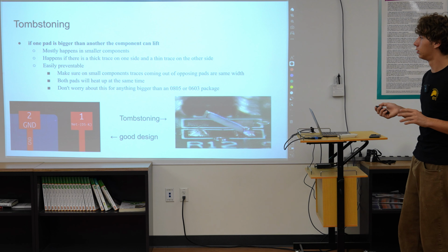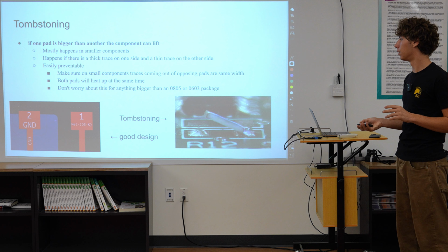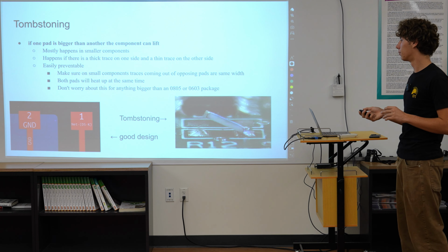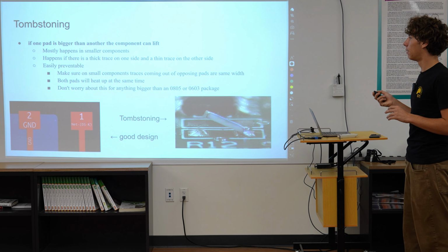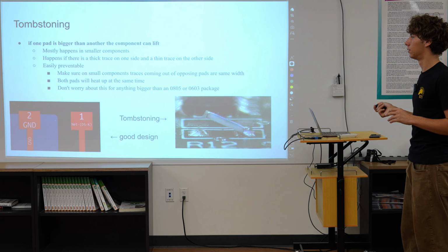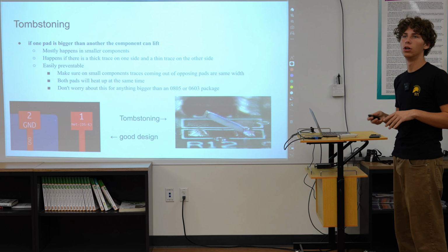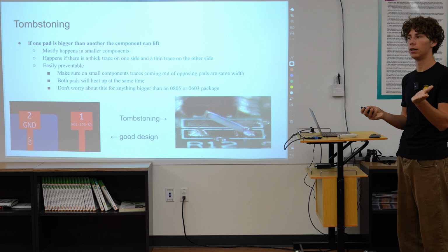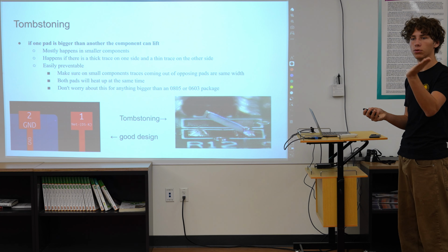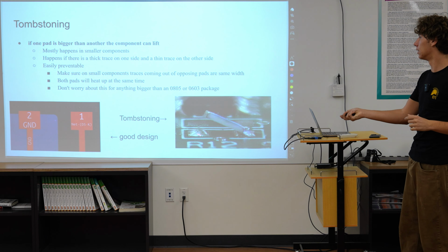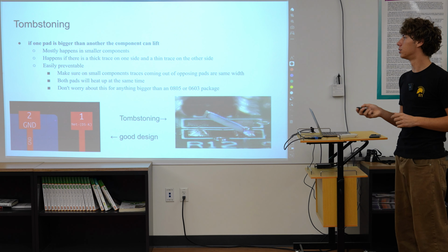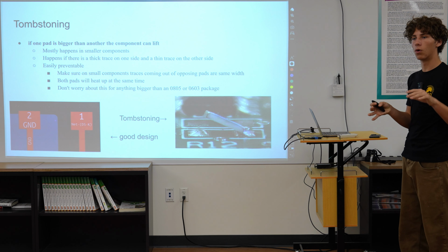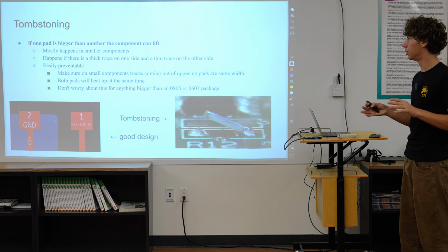Cool. So another thing that could happen if you're just getting into via design is tombstoning. This mostly happens in smaller components, but if one pad is bigger than another, a component can lift. That's because there's an uneven heat transfer. One pad gets hotter than the other pad initially, and then it'll reflow, and then eventually what will happen is because it's reflowing, you'll pull the part in and then kind of tombstone just like this. This will happen if there's a really thick trace on one side and a really thin trace on the other side, because the time it takes to warm those traces up is going to be different for each trace.